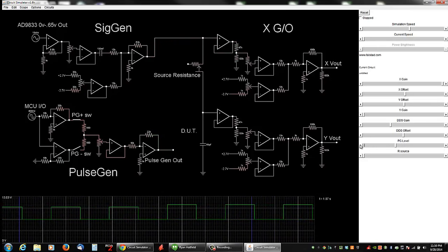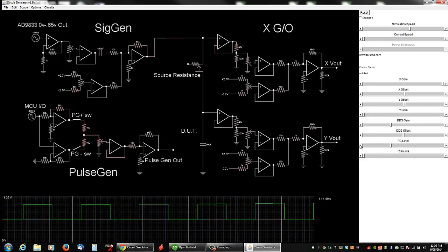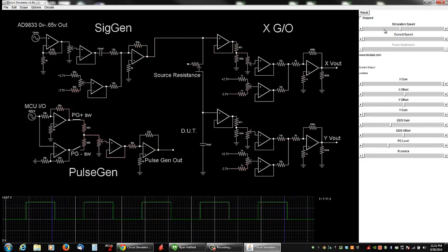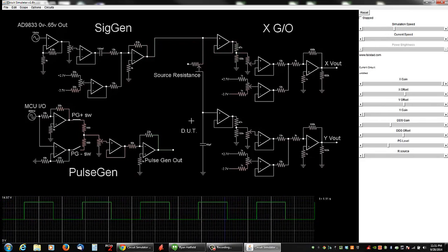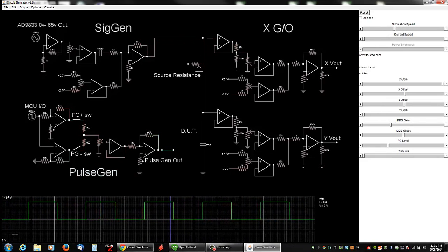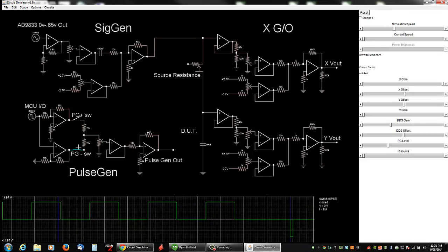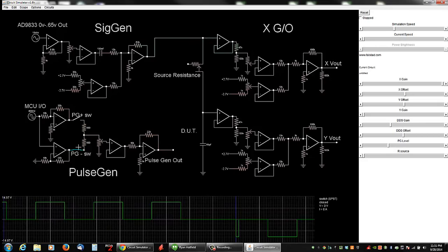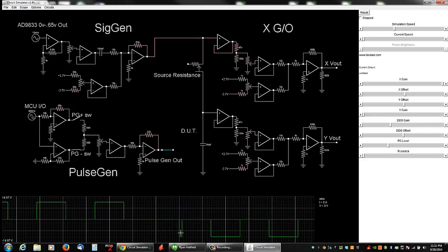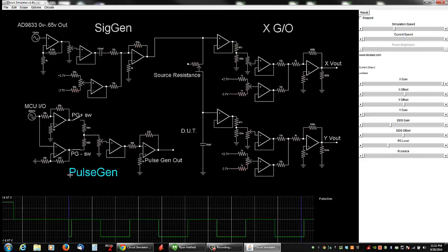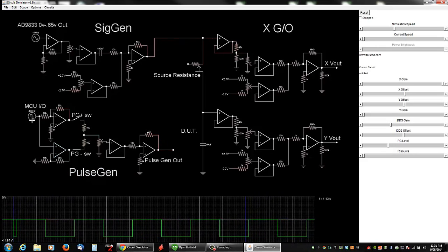Or at least find my 15 volt point, because the op amps are going to be driven off of 15 volts. Okay, there's my positive, 0 to 14.97 volts. Shut that off. Zero's out. Negative there. And it will be 0 to negative 14.97 volts. And I realize this is a simulation, so nothing's going to be perfect, but it'll be close enough.